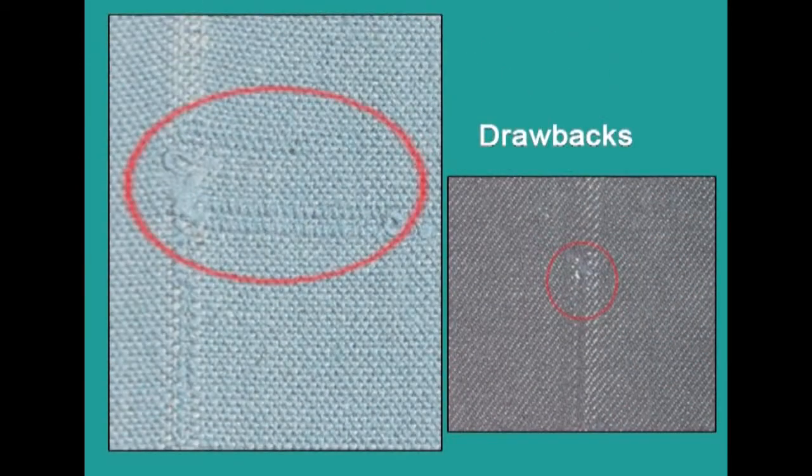And drawbacks. This is caused by excessive loom tension gradually applied by some abnormal restriction. When the restriction is removed, the excess slack is woven into the fabric. Usually the ends are broken at that particular point, and so it is considered as a major defect.